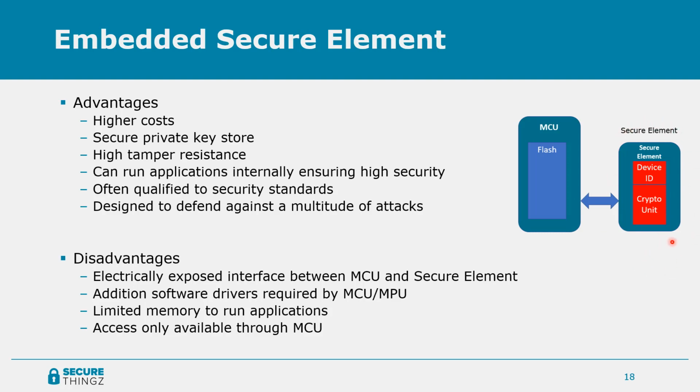The disadvantages are their electrically exposed interface, again between the MCU and the secure element itself. There are often additional software drivers required to run on the MCU to talk to the device. There's limited memory to run applications on the actual secure element, and one big limitation is you can only access a secure element through this microcontroller.